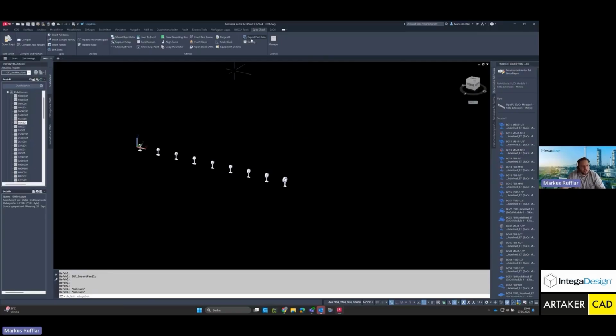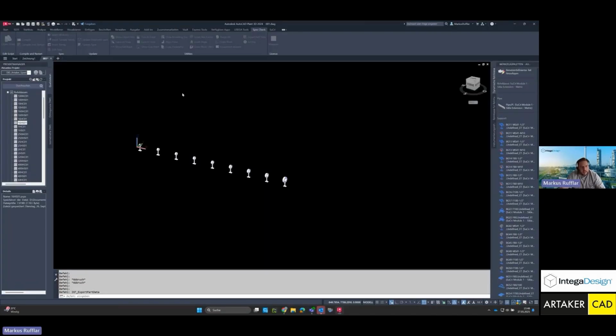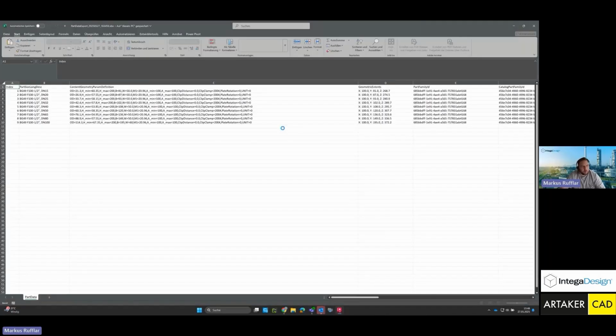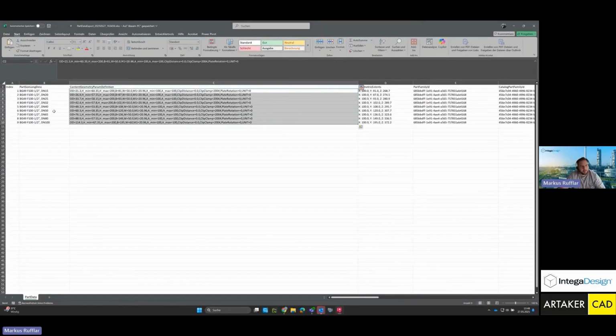And in addition, which is perhaps quite nice, if I save this here now, then I have here, and this is actually the main reason why we integrated this function, the option to display the content geometry parameter definition, meaning the parameters of the respective components with which they were created, but also the geometric extents here. So let's say you have a fittings catalog, and now you want to quickly check whether ultimately the parameters you entered here were actually used as the component size.